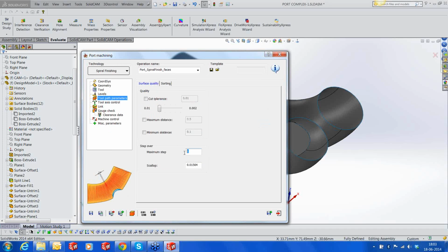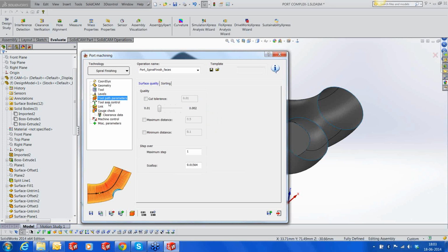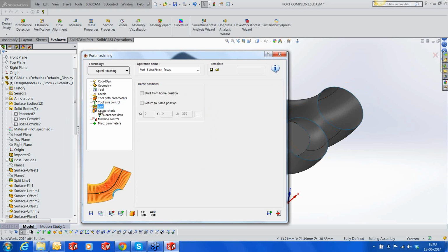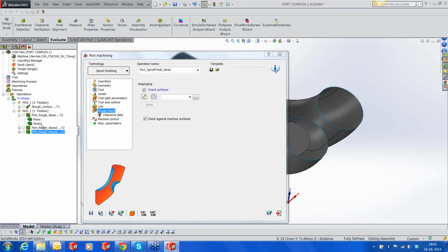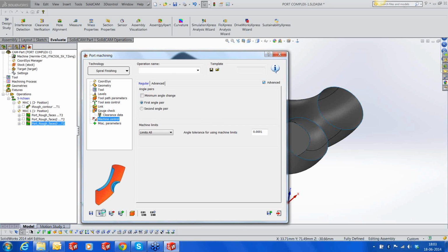Toolpath parameters, maximum step down of 1 mm, tolerance of 10 microns. Again, I'm going to go from top, maximum from top. And we're going to have climb machining in the entire spiraling operation. All right, gouge check. Again, we will select the gouge check. In this case it will be against faces 1, because that was the face used for setting up gouge checks for the top side. So it's faces 1. Okay, let's run the calculation.